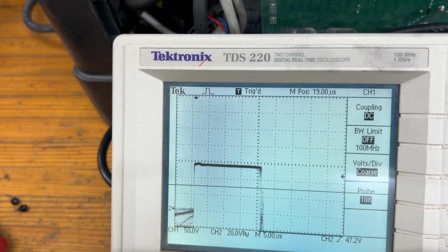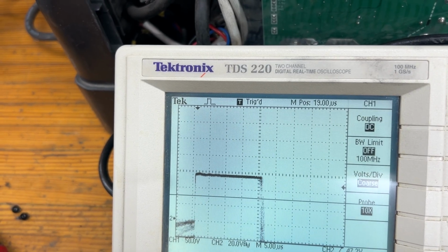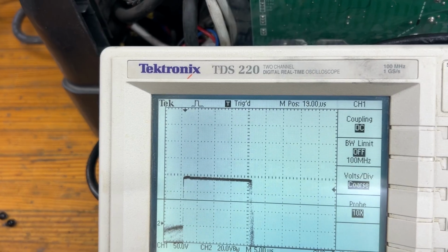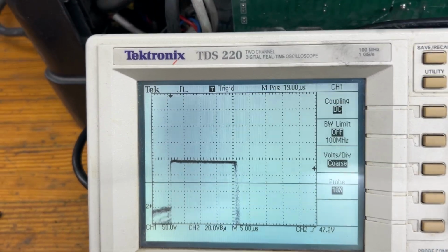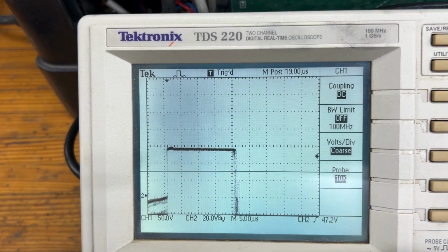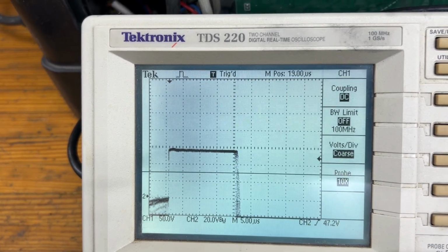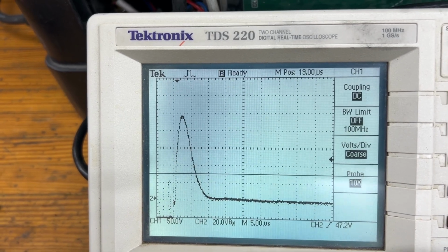Well, there's a negative offset, and then the pulse width shifts up to 20 microseconds. So it doubles, which is consistent with the behavior of the motor. It starts at a slow speed, and it increases perhaps double RPM, which is reflective of what we're seeing.